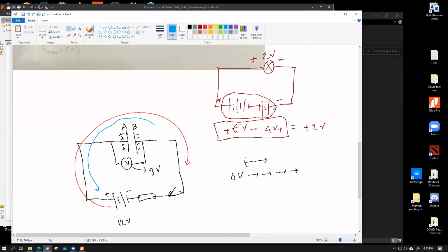but this small set of battery are going to try to produce their own current in this alignment because of their basic polarity direction. But this battery cannot do that because there is a much stronger potential provider that is connected in the reverse order. So this will become minor, or succumbed into the process, and this is going to continuously provide an opposition towards the effectiveness of this battery. That's why the total EMF of this entire source is becoming 2 volt. This source is not going to work as a 10 volt source.